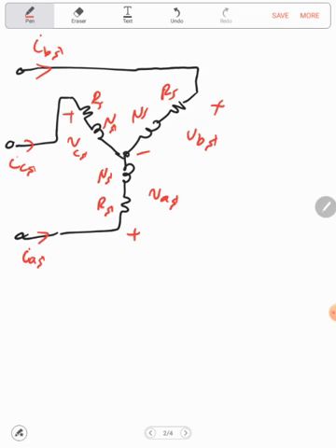Now for the rotor, I will not plot anything because simply the rotor has no physical windings. So simply there is no circuit in the rotor, and this will indicate that in terms of efficiency, this motor is a highly efficient motor because there are no copper losses in the rotor circuit. The rotor is a magnet, there is no winding on that. So if we need to write the voltage equation, we need only to write the voltage equation for the stator. So this is the stator circuit.